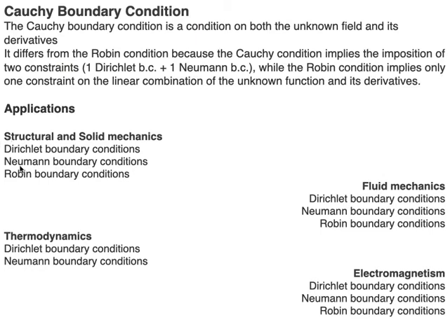If you look at a Neumann boundary condition in solid mechanics, the spatial derivatives of displacement are related to the strain tensor, and in elasticity the strain is proportional to the stress. Hence, the Neumann boundary conditions refer to both imposed strains and stresses, since the stress is also linked to an external force through the Cauchy stress principle. The Neumann condition is also used to apply external loads.